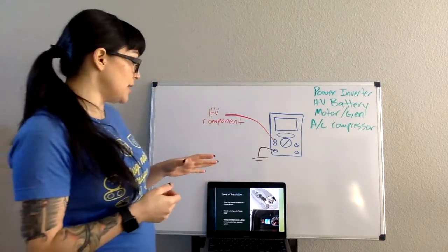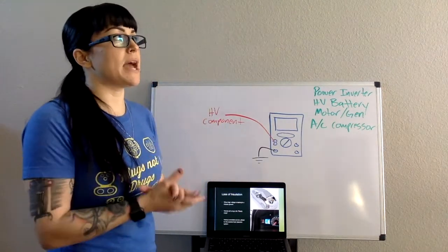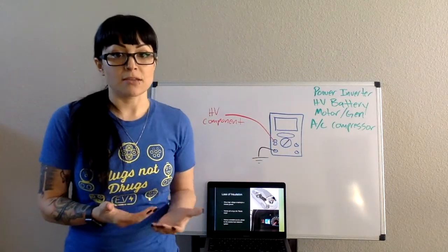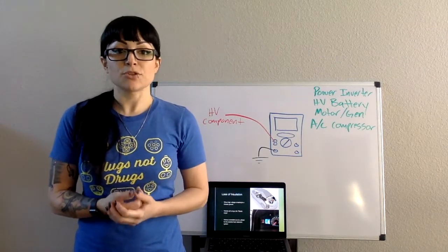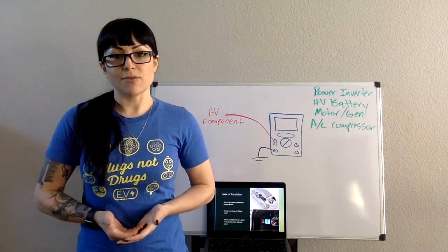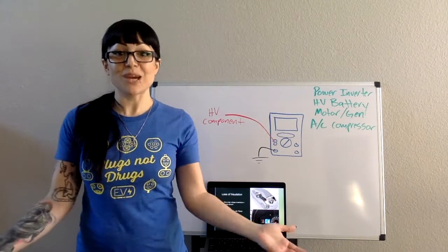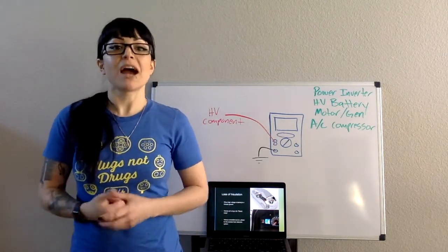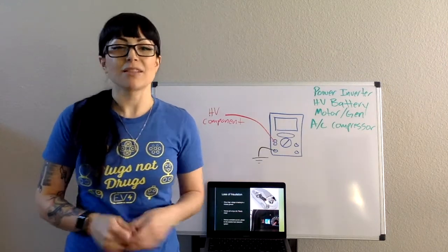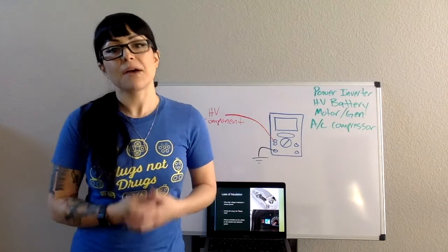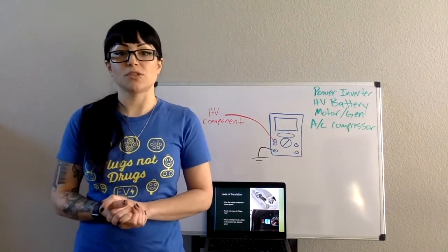what we want to look at here is how does that happen? Because in a normal low voltage system, we use chassis grounds, we use engine grounds, things like that. Well, in high voltage, we can't do that because that could be quite dangerous if you touch any piece of those components and we've got really, really high voltage. That's going to hurt, right? Low voltage, no big deal, but we can't use that type of ground. We have to insulate everything on a high voltage system.